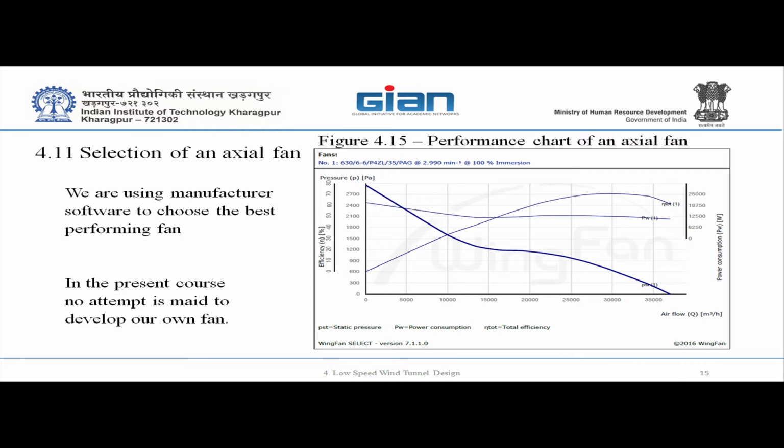You choose one of the fans and you start to calculate what happens to the velocity that you intend to have, and see what the losses are and what final velocity you get. If you get lower velocity than what you designed, then you have to look for higher power and so forth. So generally, what is the factor between losses and the jet power? Roughly, I'm saying the losses are like 25% or 30% of the jet power.